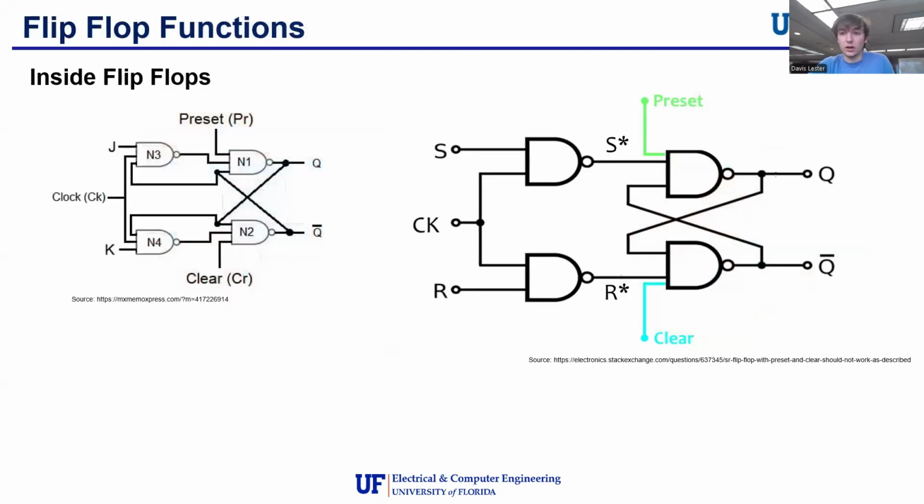So now we'll go into flip-flops. Flip-flops are extremely useful as you'll use them for a lot of state machines and counters. Now, you don't need to know what's going on inside the flip-flop, and in fact, it's pretty complex, but I think it's cool to note that every flip-flop has the similar S and R function on the right, but then I have some assortment of gates that'll allow for preset, pre-clear, and J and K and clock.